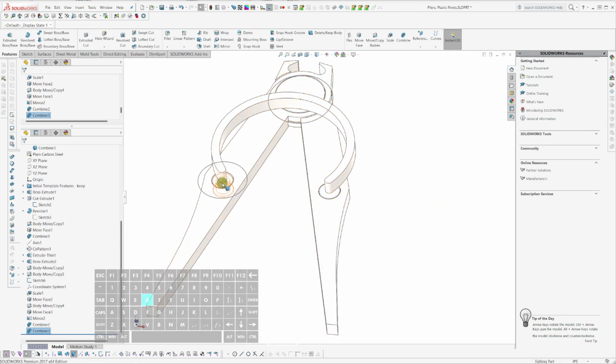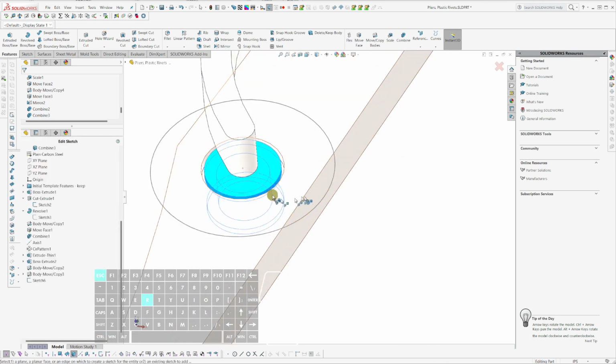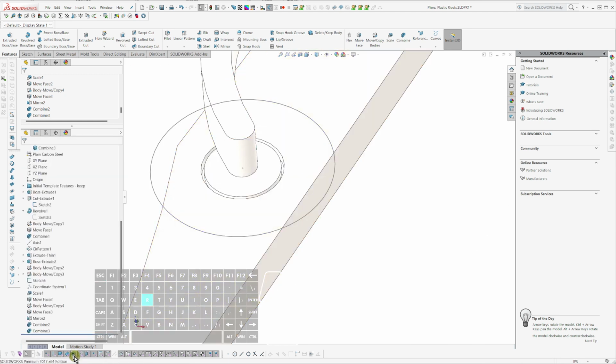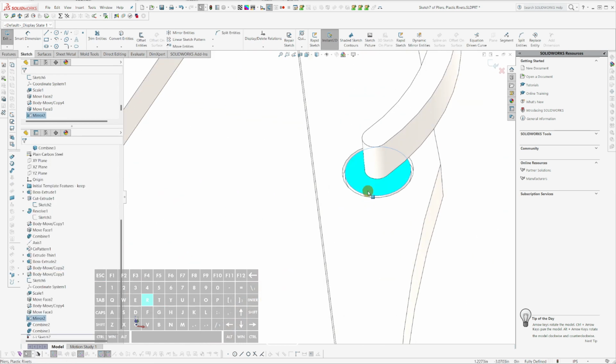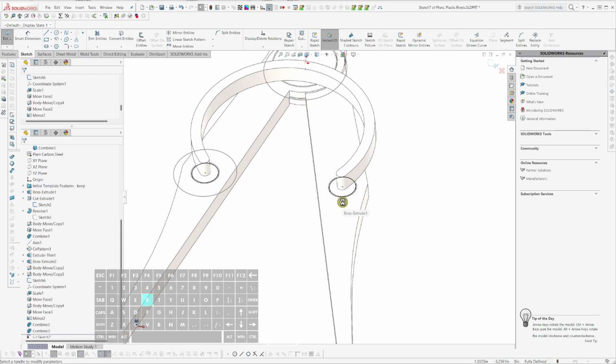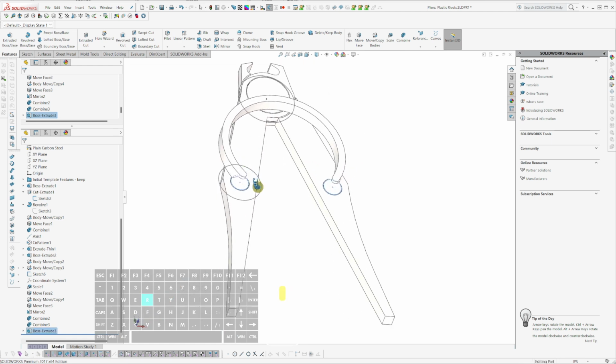But then I need to connect the hinge to these guys. So I'm just going to put a sketch on here. Oh, because I'm in selection filter. Sketch here, G for convert. Select here, G for convert. Extrude. Draft. And I don't know, 30. Yeah, we'll call it good. I think if I combine all these, if I merge results, I think it'll only merge to the hinge, which is what I want.